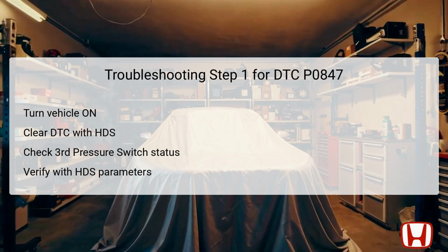Begin by turning the vehicle's ignition to the on position without starting the engine. This action powers up the necessary diagnostic systems. Next, clear the existing DTC using the Honda Diagnostic System, HDS, which resets the stored codes in the system, allowing for fresh diagnostic data collection.